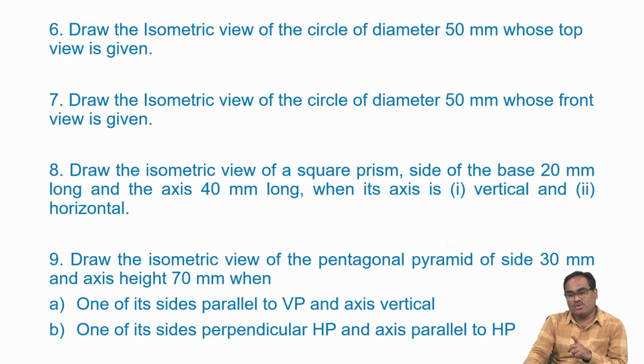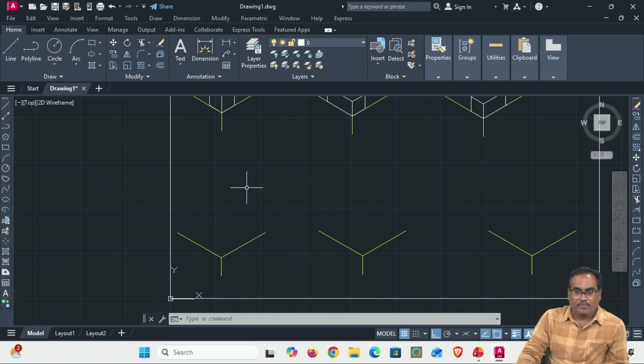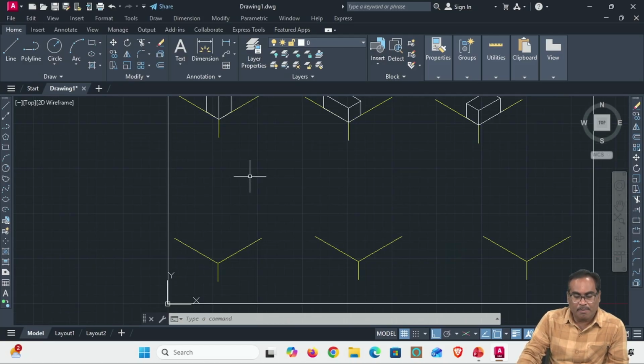That box you have to transform into isometric axis and then draw arcs on the pentagon, and all the arcs I have to transform. First of all draw the pentagon, then okay I'll show you. So go to AutoCAD window. First of all I want isometric axis. I'll copy isometric axis. I need not draw again and again. Okay, first I have to draw pentagon.